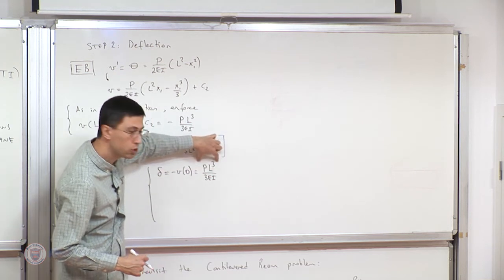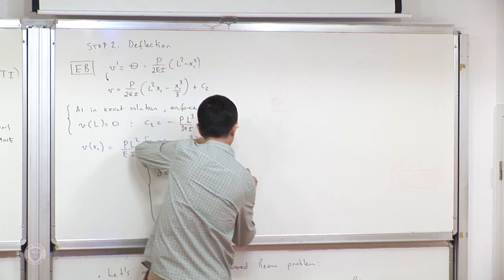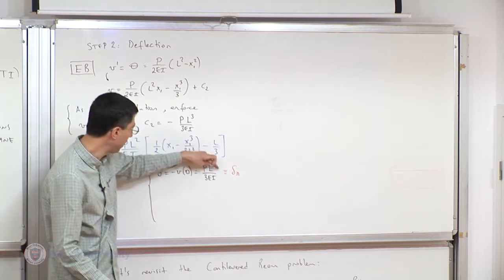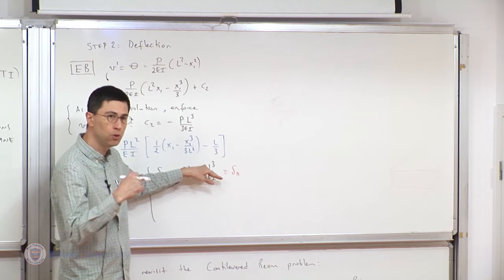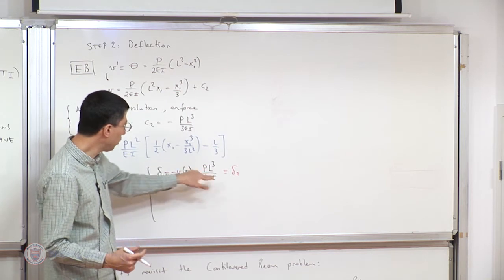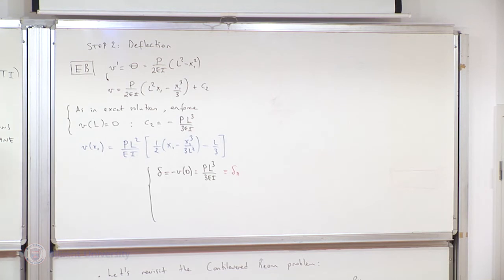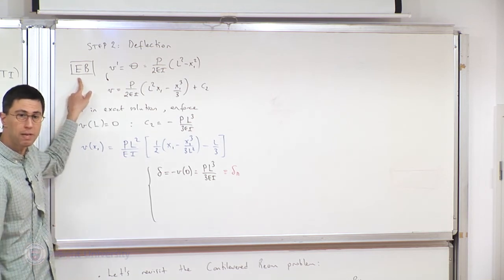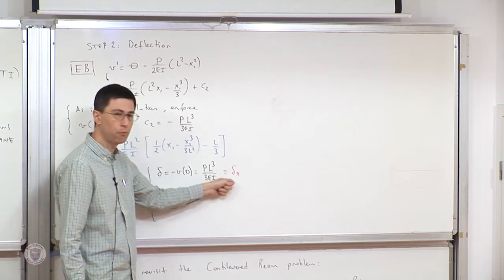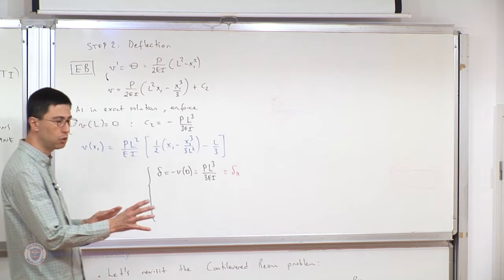The first term, and it's this term actually, is what we called delta n in the analytical solution. And we said that that portion of the deflection, delta n equals this, comes from the influence of bending moments. And the second term comes from the shear force. And so here, we don't have the second term, which reflects shear force effect. And indeed, we already said that the beam theory, Euler-Bernoulli beam theory, is omitting the influence of shear stress, and it is only exact if we have a pure bending scenario. And therefore, we capture the first term exactly, but the second term is not there.